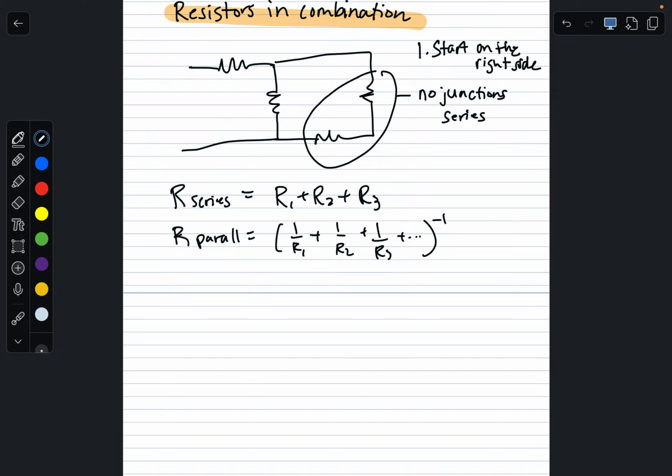For voltage, for charge, and then you can use your fundamental capacitance relationship to convert those values to anything else. C equals Q over V. You could also use V equals IR if you were asked for the current through the resistor.